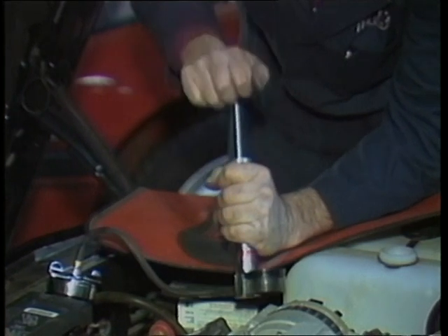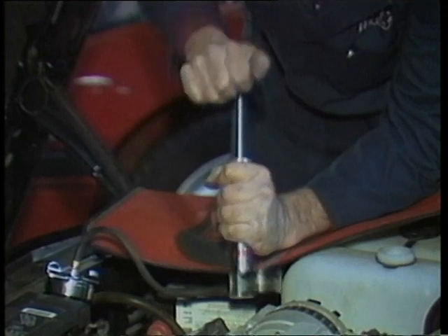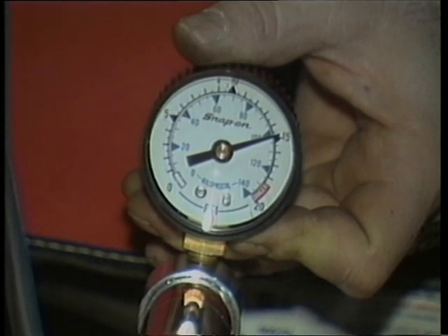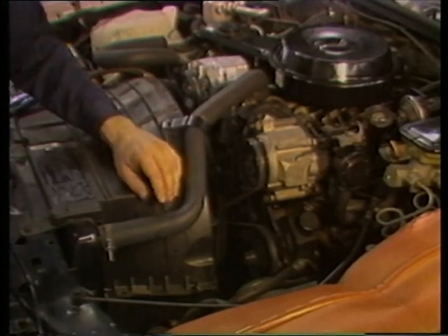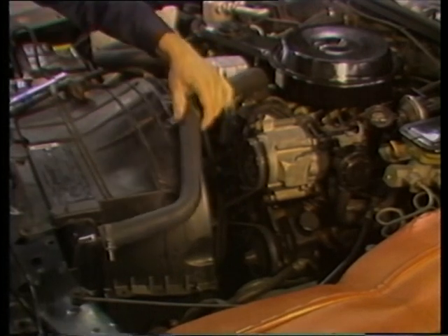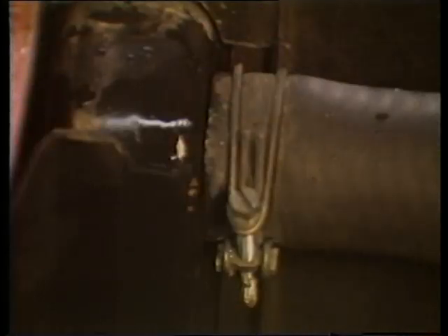If you have the correct cap, read the numbers stamped on the top of the radiator cap. Don't go beyond pressure specs or you could damage the radiator and other components. With the system pressurized to specifications, or about 15 pounds per square inch, check for leaks. Look around the radiator, gaskets, water pump, freeze plugs, and hoses.